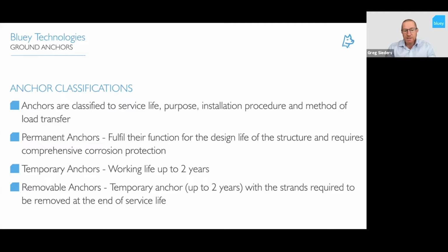Removable anchors are classified as temporary anchors as well, for up to 2 years working life, but where their strands need to be either removed or able to be cut through later on after their service life is finished.